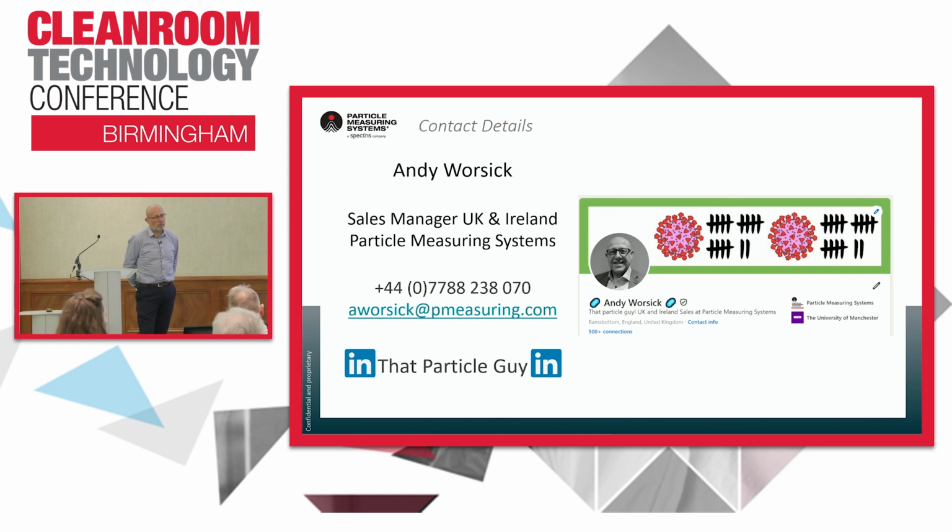This is part of process monitoring. In life sciences, everyone wants the continuous monitoring probe facing upwards at the HEPA filter. The HEPA filter is not ever the risk, unless the unit's off or the filter fails, which really shouldn't happen. And the times we place the probes facing towards the risk, we've gotten hits on it, so no one does that. I just wonder what your thoughts are on that.